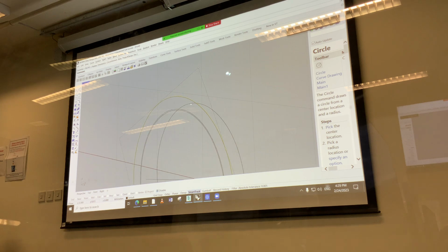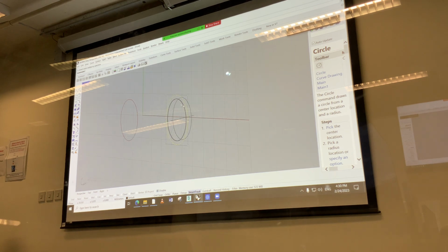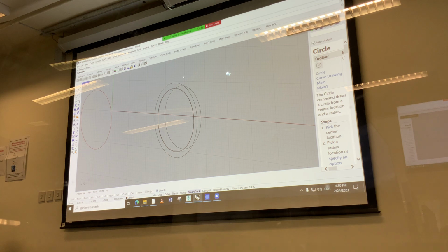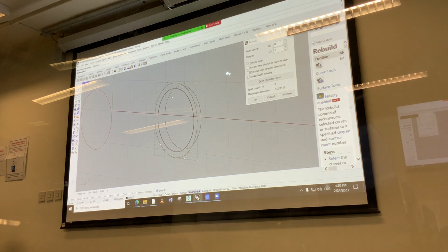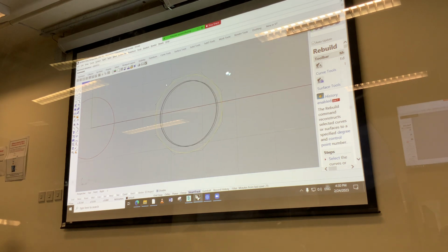So now we delete this guy here. And then if I select this guy, you see that actually now the control points are completely symmetrical. And that will stay even if we copy this, even if we rebuild it, as discussed, with 8 and 2, the same count as it is. You see, tada, it stays symmetrical. So keep doing things symmetrical, not symmetrical for design purpose, but if you are having your control points symmetrical, everything will be easier.